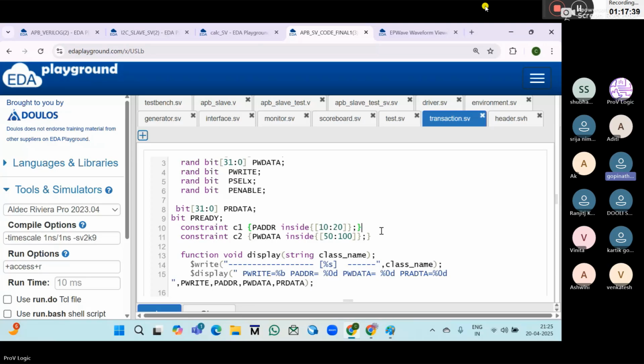I have one question. If I want to add one more slave, like the APB slave test, now I want to add a dual port RAM, dualportram.sv. Okay. So only the instantiation will change, right? But I need to write the APB system separately, the RAM separately, and both you need to connect in the top level, whatever design.sv.